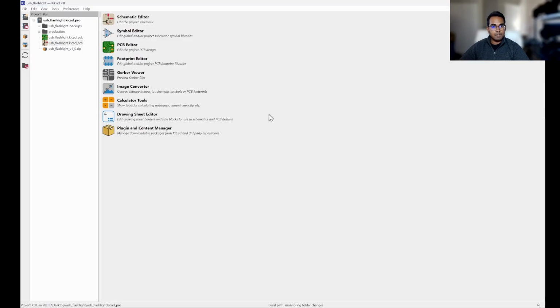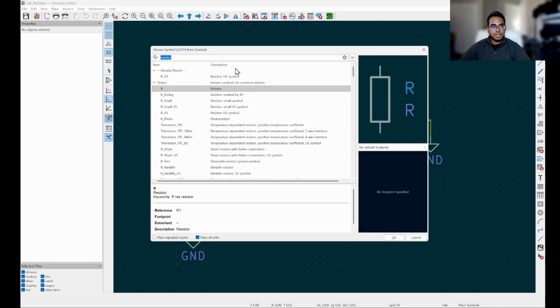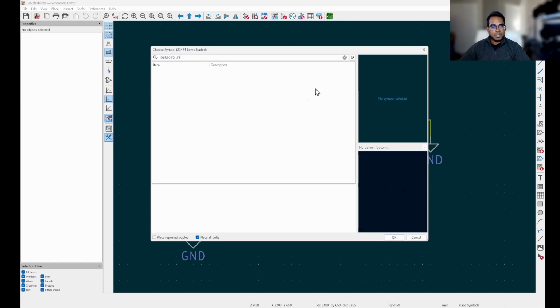This one right here. I'm going to copy and paste it into my symbols menu. You'll see that there are no results because this is a highly specific part that maybe was more recently announced, or maybe it's just not so common that the KiCad developers decided to include it for everyone to have access to as soon as they download the program.